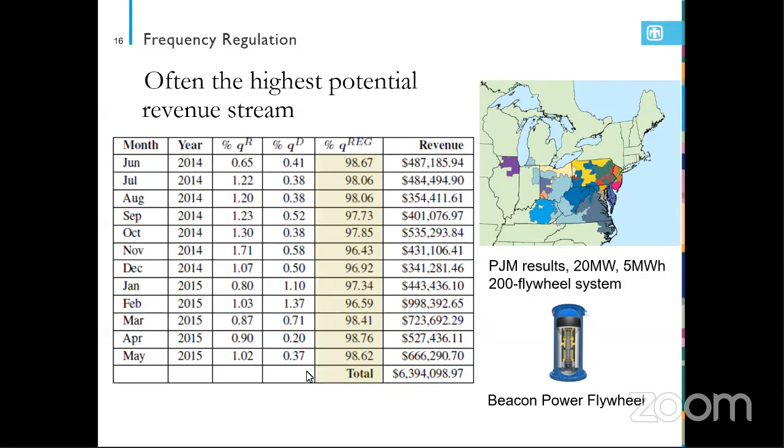But one comment about frequency regulation markets is they're usually relatively small with respect to the size of the energy market. So usually it's only like maybe 1 to 3% the size of the energy market. So because it's small, it is more sensitive to having new people come into the market, which reduces the prices. And we have seen this in PJM.